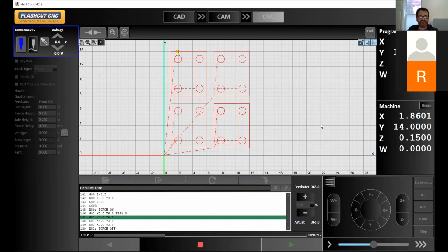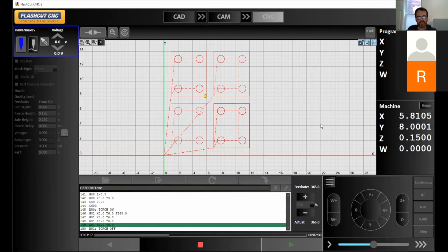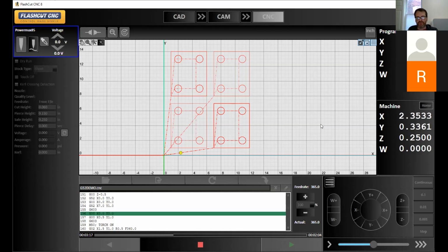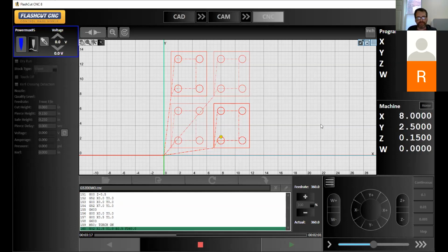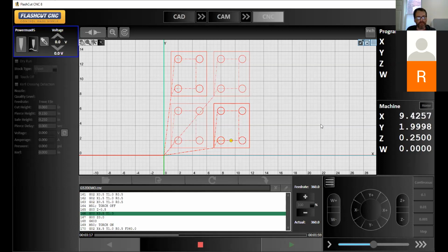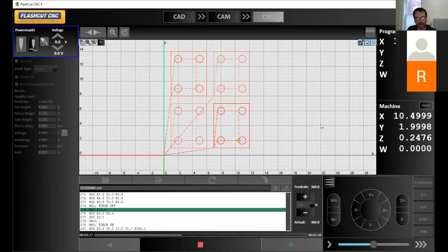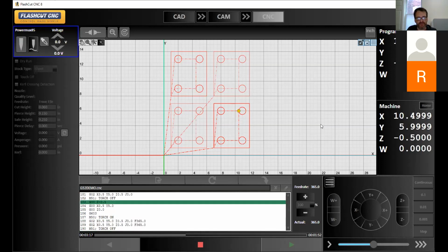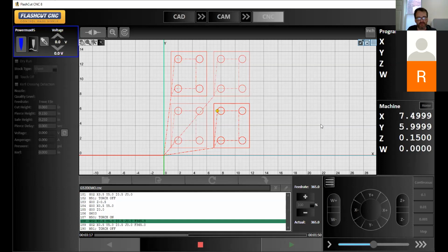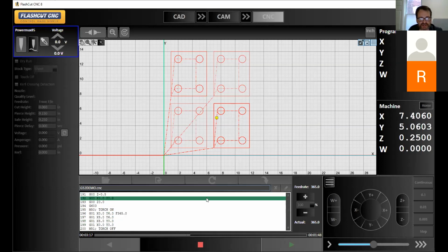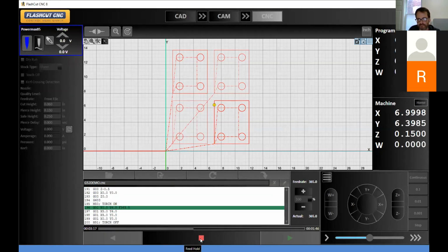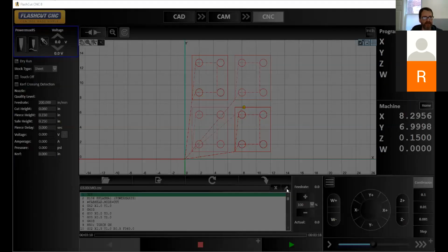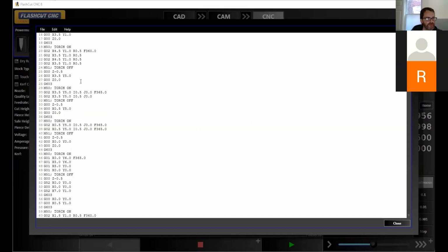The whiteboards that I send you, you'll notice in my manual programming, I've used a combination. The first two, I use the R method for programming the circles. The second two, I use the I, J method. I'm going to stop this, refresh this, and we are going to take everything out up until